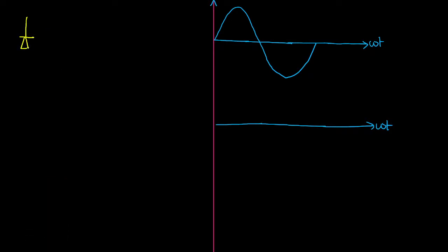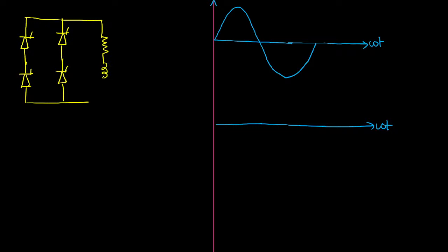Fully controlled converter means it will be having 4 switches basically, and the 4 switches will be controlled by a firing angle alpha. A single firing angle will take the responsibility to control these switches. And in the output side, they have connected RL load. Then they have taken one source simply. One terminal is connected here, another terminal will be connected here. This is the basic circuit.